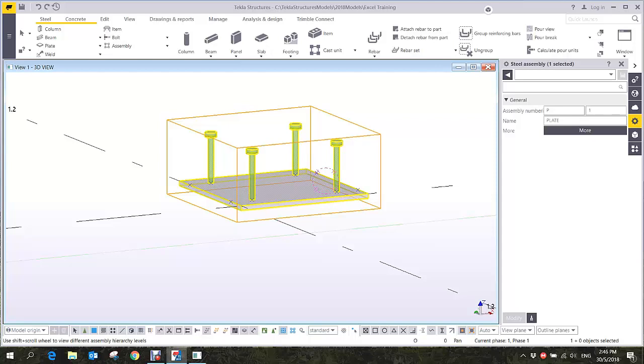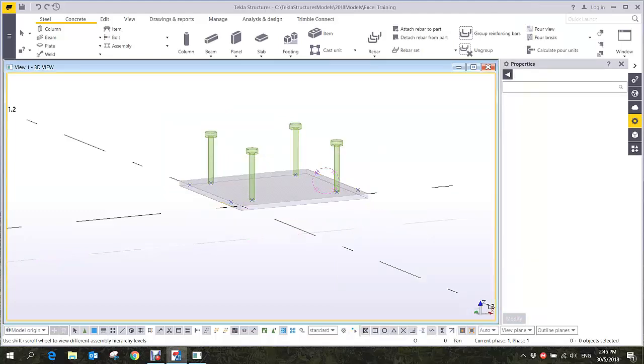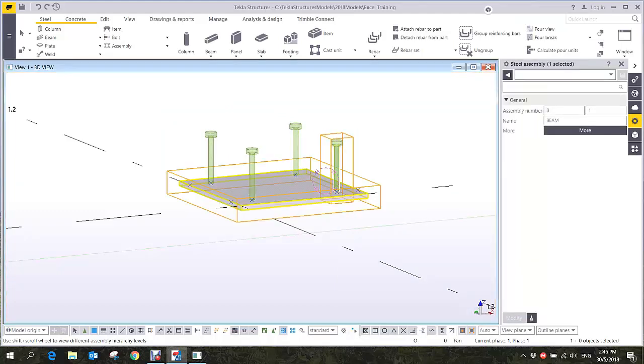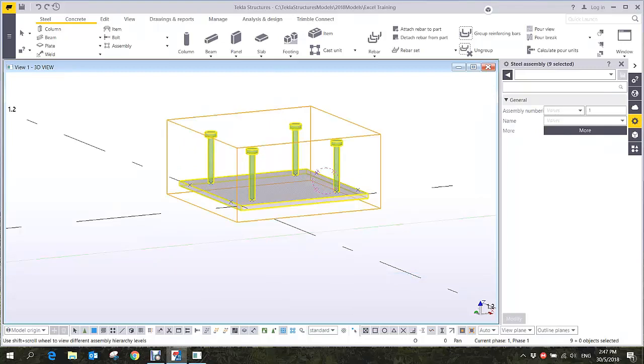Can we put it individual? Can we break it to individual? Yes. Just simply right click, assembly, explode, or remove from assembly. Explode is individual. Okay, but here I cannot select which to separate from the assembly, right? Let's see. Assembly, make into assembly. Okay, that's one assembly.